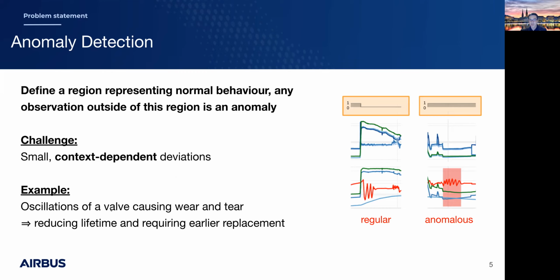You can imagine this is a valve somewhere, and this valve is still, it's not breaking the airplane, it's operating. The plane is always safe because we are speaking here about small deviations, nothing which is safety relevant. But still, this means that there is an opening and closing of this valve many times per minute. And of course, the valve is designed for a nominal amount of opening operations. And if you are operating it continuously without need, then the lifetime of this part reduces.